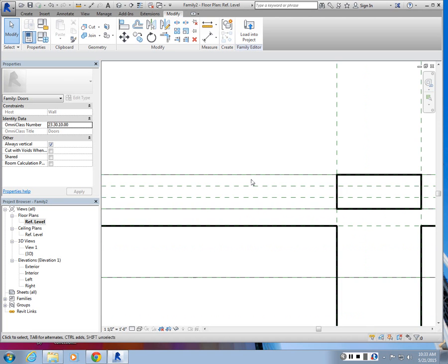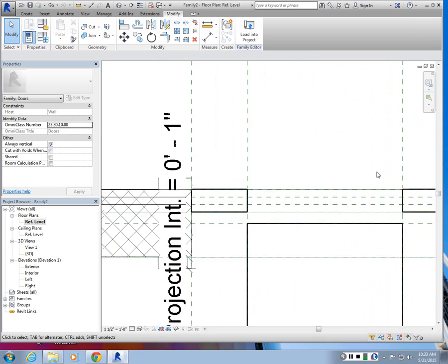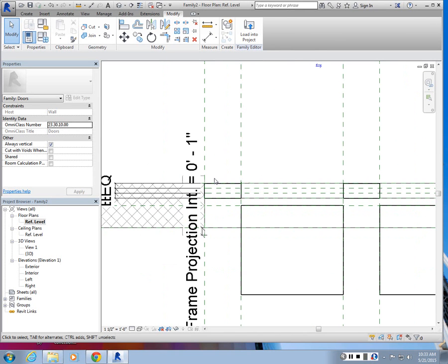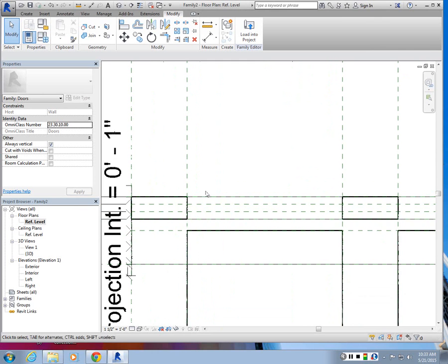Right? So basically, we are controlling the whole width of the door, and then I have these 2 offsets that are at equal dimensions. So I included this annotation. So however I change the thickness of my door, I will have those 3 equal offsets. So the glass panel will stretch a bit as well. If you don't want that, you could just create some dimension here and lock that dimension so that it will be just fixed. You don't have to parameterize the thickness of the glass panel.